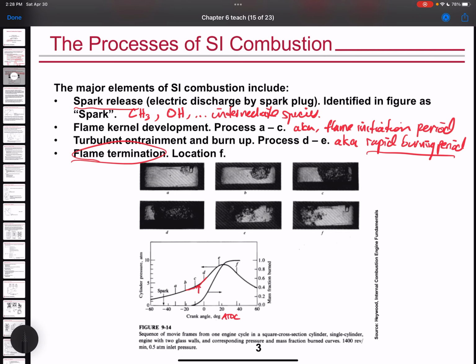And so once we know the heat release, that is the amount of energy that is converted by the combustion process from the fuel, and we know the mass of fuel that's been delivered to the mixture, that then allows us to calculate the mass fraction burned, right? And so mass fraction burned is more or less telling us, I'll often refer to this as MFB, the fraction of fuel burned at any given moment.